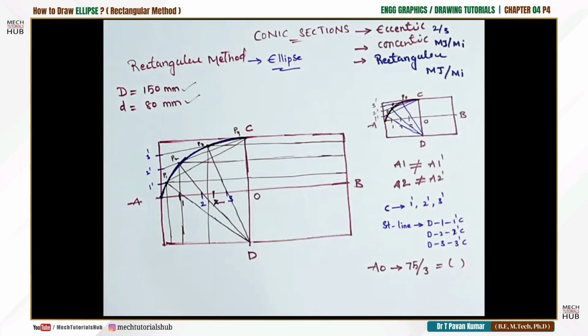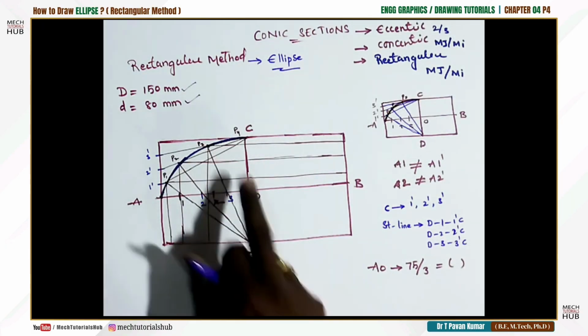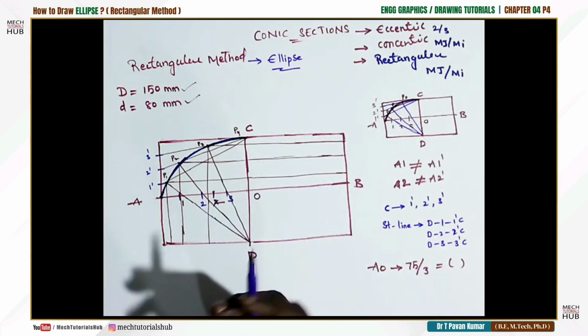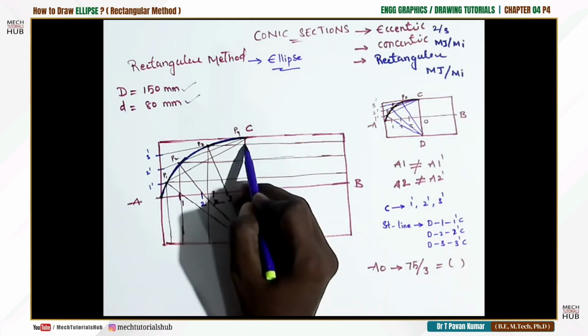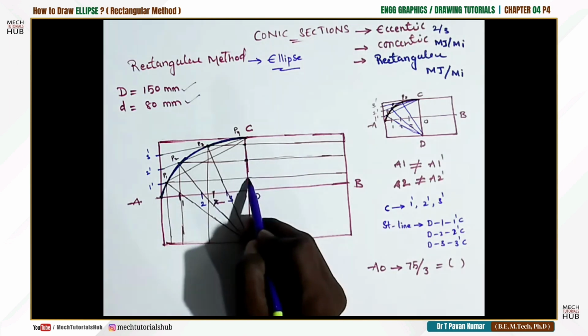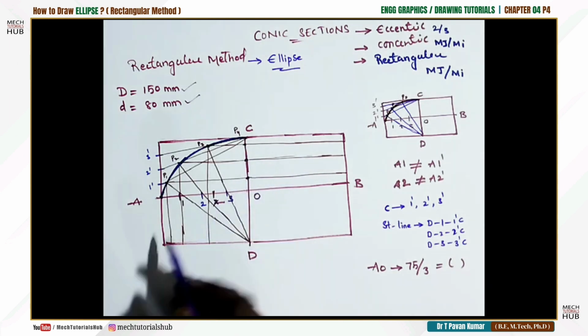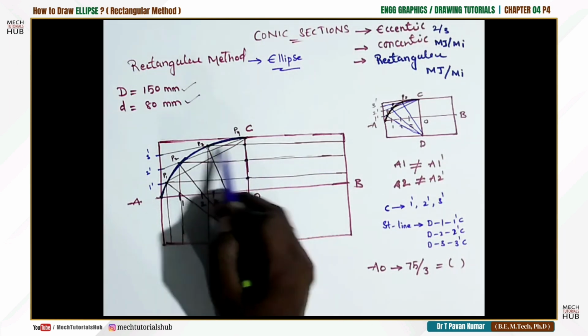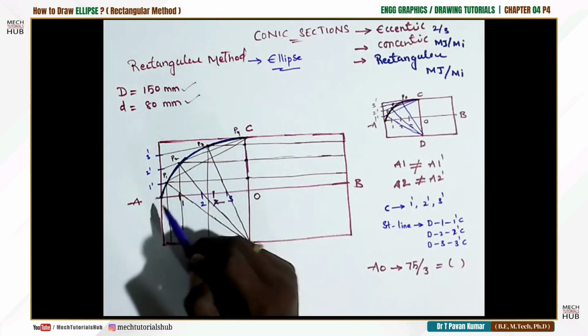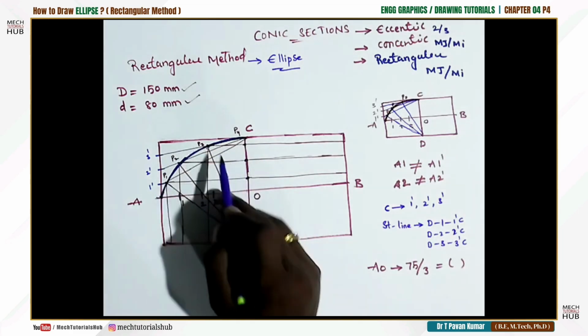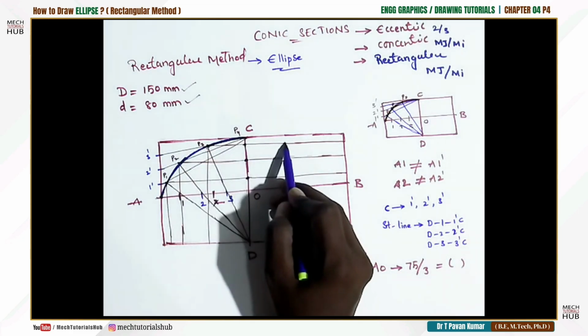Okay, something like this. You got quarter half. After getting this quarter half, whatever the extensions or locuses you have drawn, measure a distance from this vertical, wherever this horizontal is intersecting, from this point. From here to P3, measure the distance of point to P3. This has center, make a mark. This distance should be equivalent to this distance.